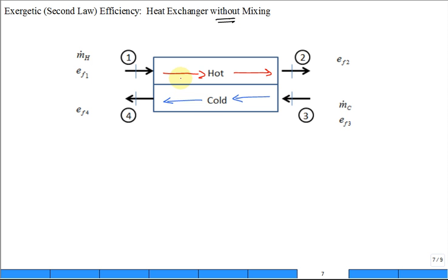Do we have heat transfer this way inside the heat exchanger? But they call it an adiabatic heat exchanger. The first time you hear that, you think, what? Adiabatic means no heat transfer. Heat exchanger, that sounds like a dud. But it's no heat transfer with the surroundings. Heat transfers inside, but not to the surroundings of the heat exchanger.